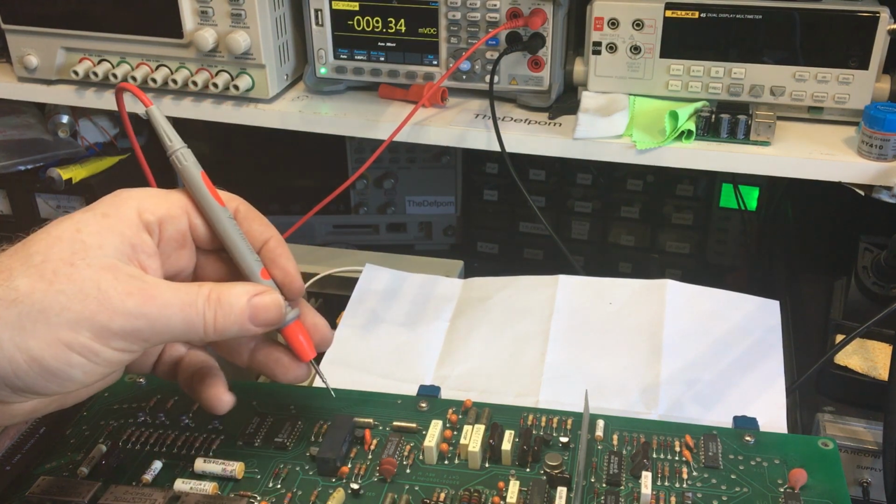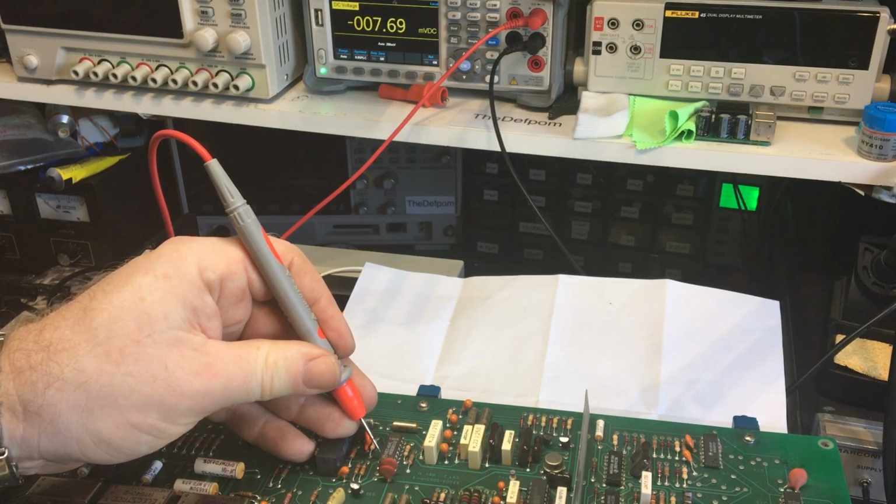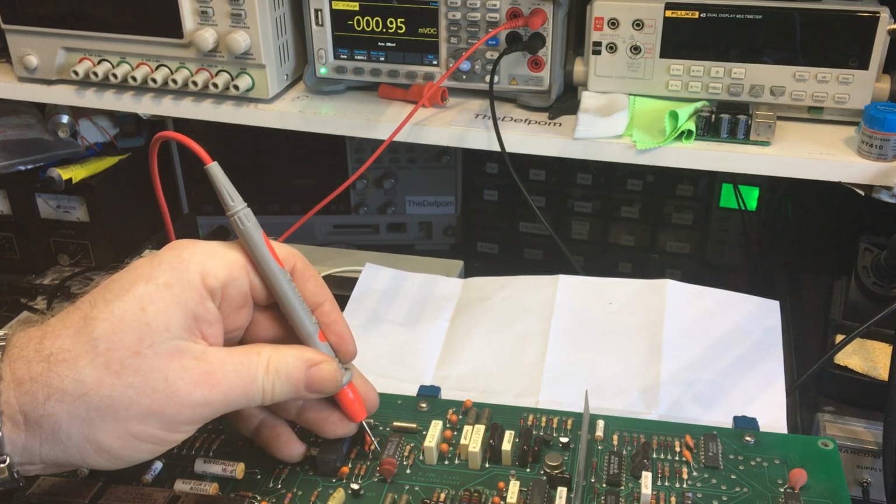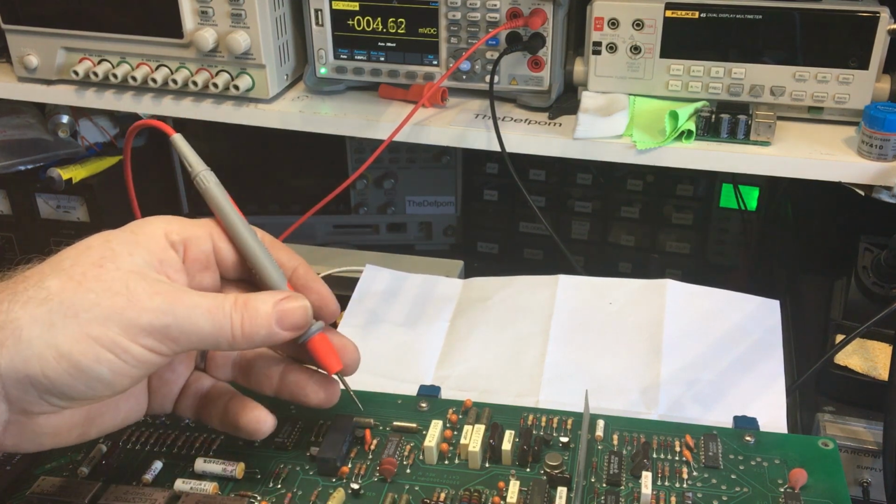That's fine. Now, if I measure the pin on the IC, which is pin 14, you can see that is also switching. Now, what's happening is it's shunting it to ground, right? So when it's off, it shunts it to ground. That's it. That's disabled. And when it's on, it lets it float. So anything that passes through will come through.